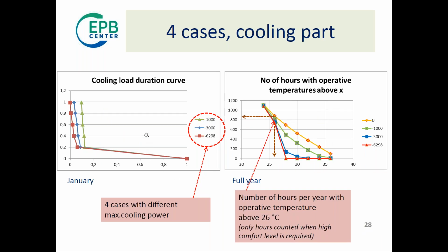And on the other side, on the cooling load, if you have an undersized cooling system, in this case 10% of the hours it runs at the maximum cooling load. And in that case, it's the green line here. You'll have high temperatures, so you exceed the maximum temperature set point, which was in this case 24 degrees. So this is actually just a teaser for the next webinar when we'll show more results.